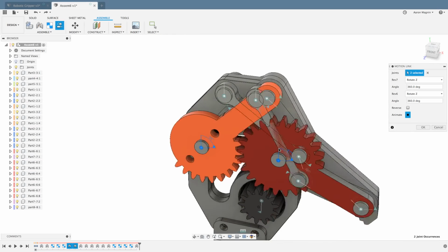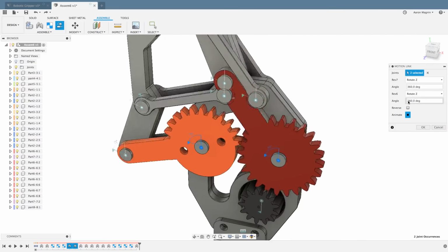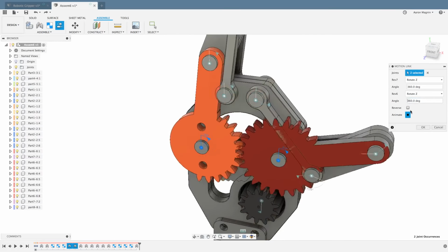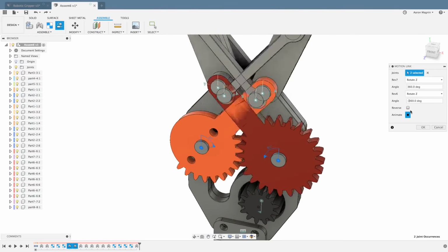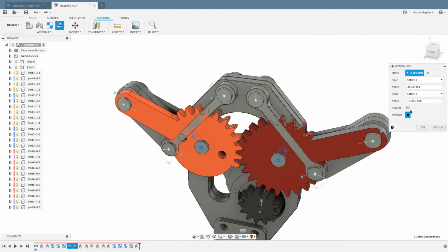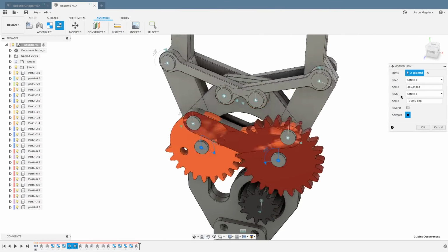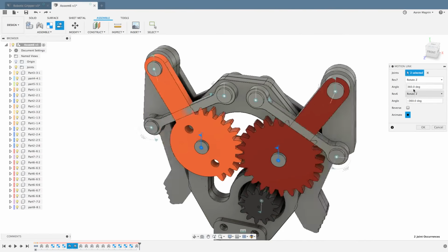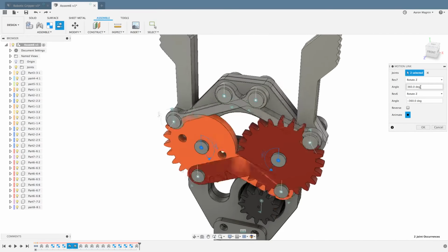I really didn't input anything, so it's not really my fault. I'm gonna blame Fusion for this, but instead of obviously rotating together, you want these to kind of rotate opposite to one another. So we'll make this second Revolute 6 angle negative 360 versus positive 360, and this could be 1 and negative 1. It doesn't really matter.